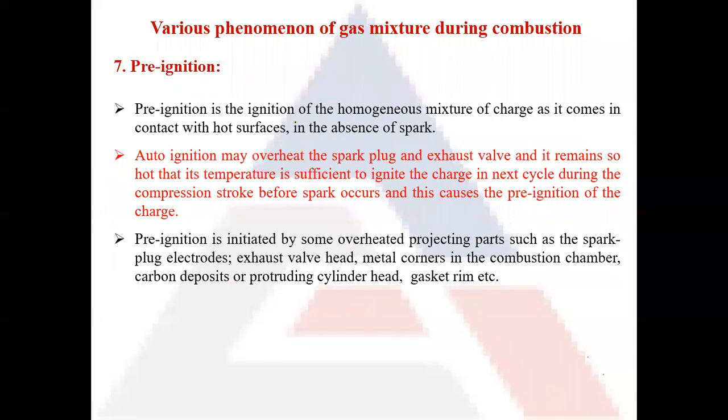Now after auto ignition, there is pre-ignition. In this case, what happens is that from the previous ignition, or the deposition of carbon on the various parts of the combustion chamber, like on the edges of the piston, on the edges or electrodes of the spark plug, or the edges of the fuel injector in the case of a diesel engine, those edges from the last combustion or the heat might be glowing red hot.